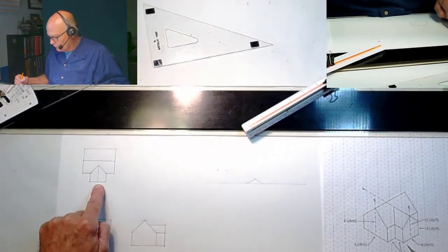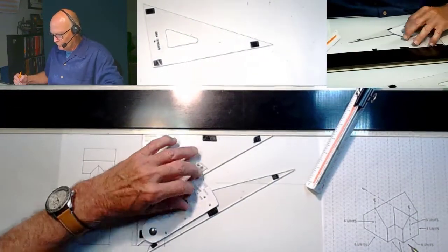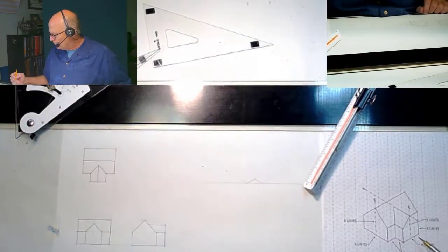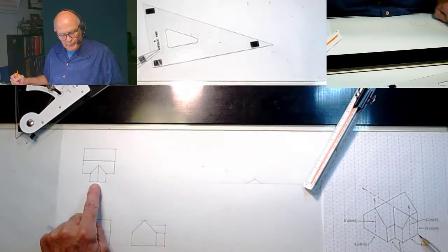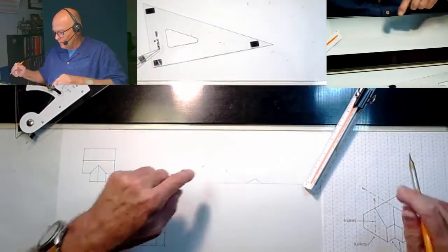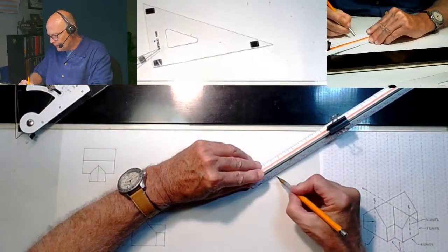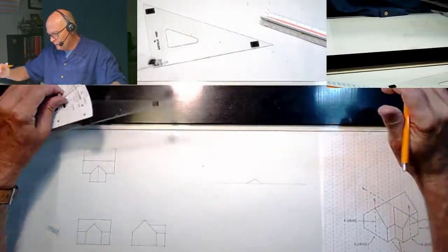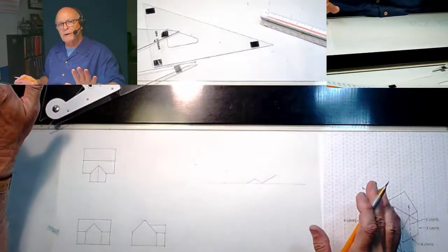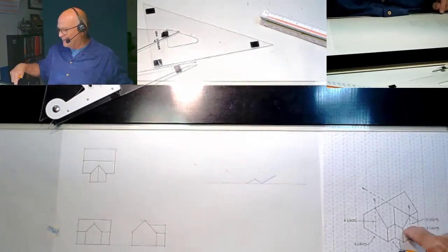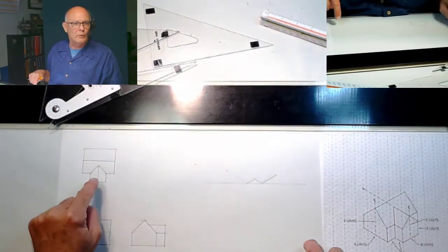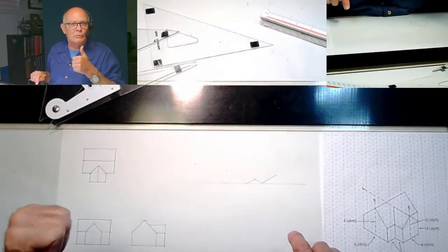Again, 30 degrees. So using my triangle, setting it, and going up at a 30-degree angle. How far? Measured from here, 4 units, same as over here. Everything's the same, so we just measure, and we do the 4. Mark it, draw it. Now, it gets a little funny. We're going to flip around to the back side. Not everything is viewable from here, but everything's easy to see from here. So we can follow this drawing because it is correct.